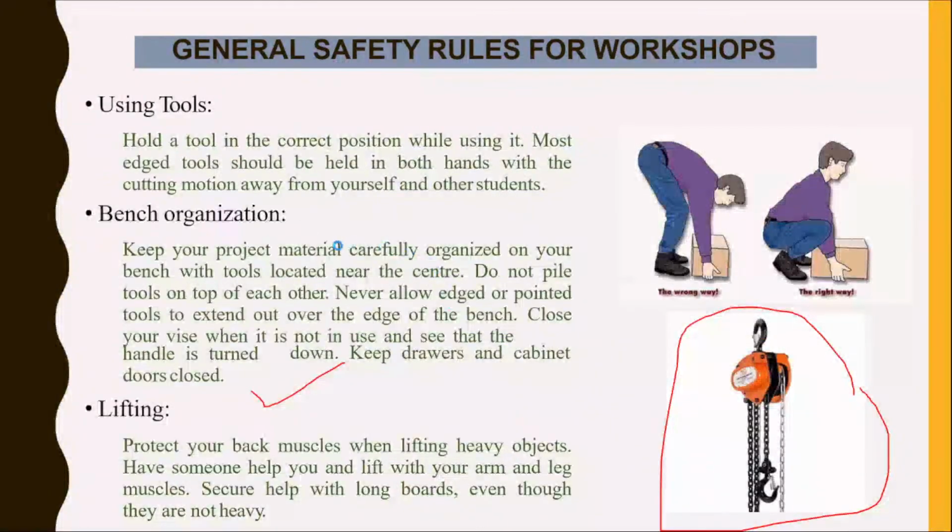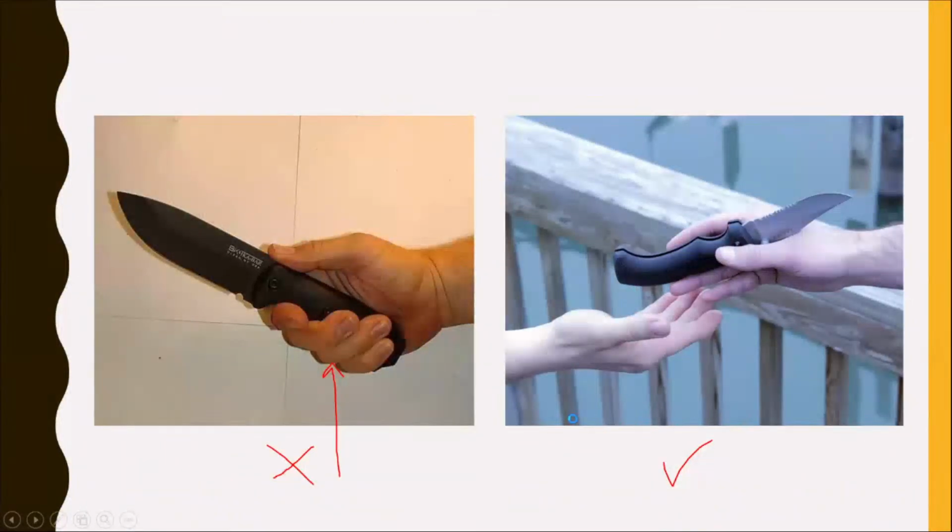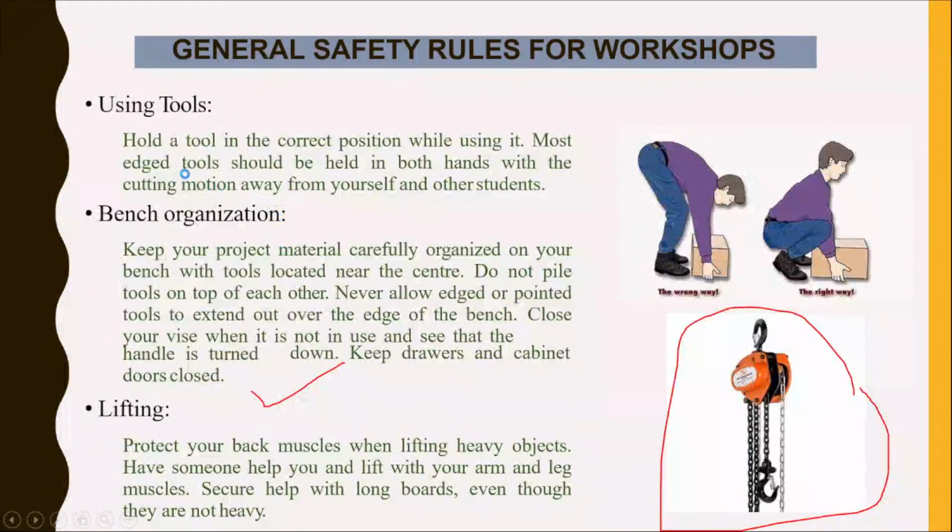Then using tools, hold the tool in the correct position. What I have told here is that most edge tools should be handled with both hands, with the cutting motion away from yourself and other students. So you have to point your tool away from the people.